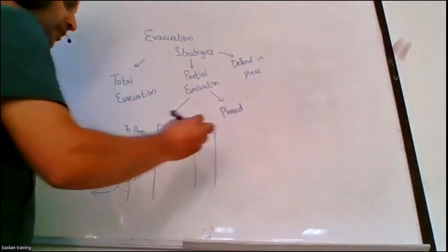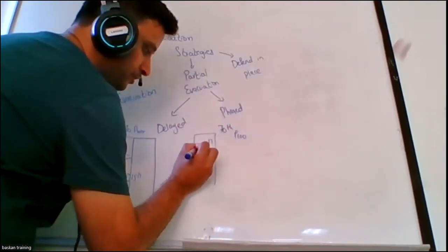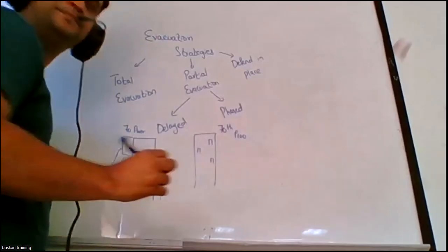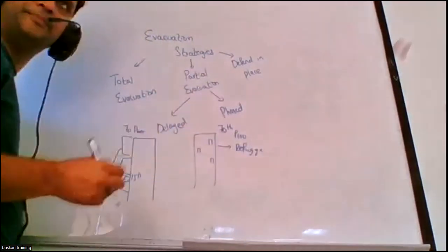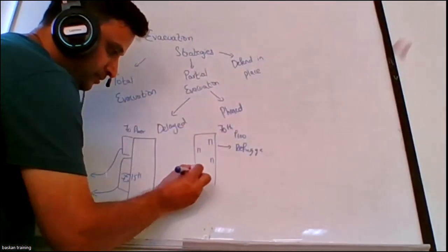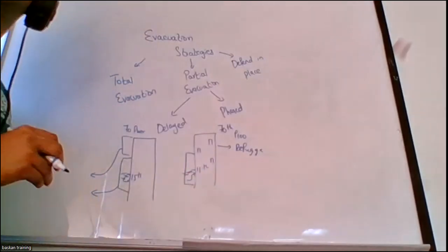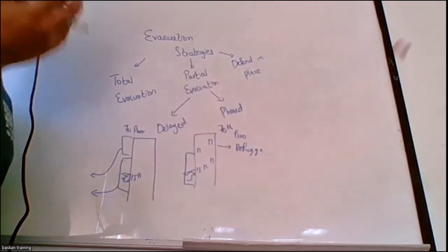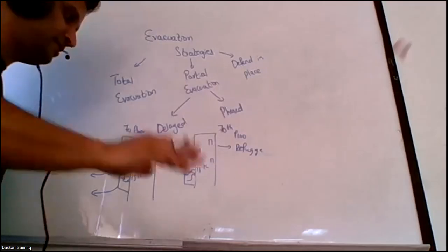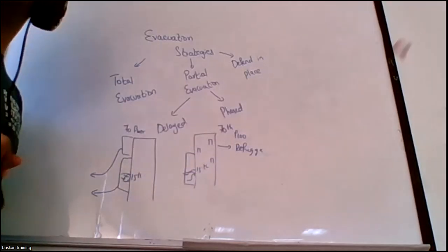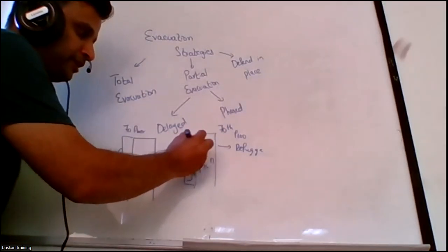Same situation, a 70-floor building. But here I have compartment rooms, refuge rooms, where you can of course take refuge for the time being. So a fire breaks out on the same 15th floor, and the people near the threat are evacuated. Now I don't unnecessarily need to evacuate everyone, because this call can be made by the fire chief marshal outside. He thinks it's not going to propagate that much, so he will just say that people on the other floors should move into the compartmented rooms.